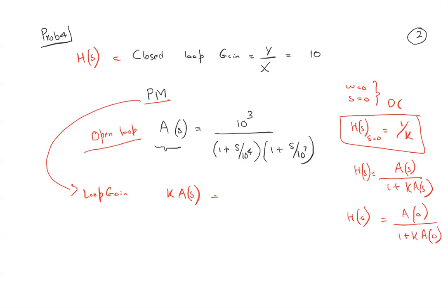Normally when we put A of 0, meaning the gain of a system at a 0 value, we take it as a very big value, so infinity. When A of 0 is infinity, the result will be approximately equal to 1 over K. I will give you an example at the end of the lecture. If you have any confusion, I will give some description about the omega bandwidth and omega unity. We already talked about gain bandwidth product previously, but again, I will reiterate the same point.